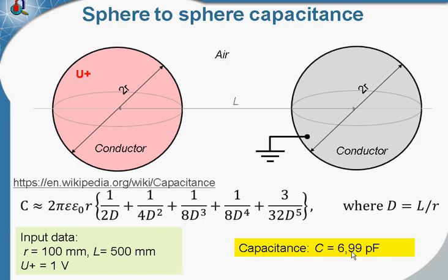What is the reason for such large difference between calculated and analytical results, and how to amend this difference? The difference is caused by the poor mesh quality, and to amend the difference we should adjust the mesh.